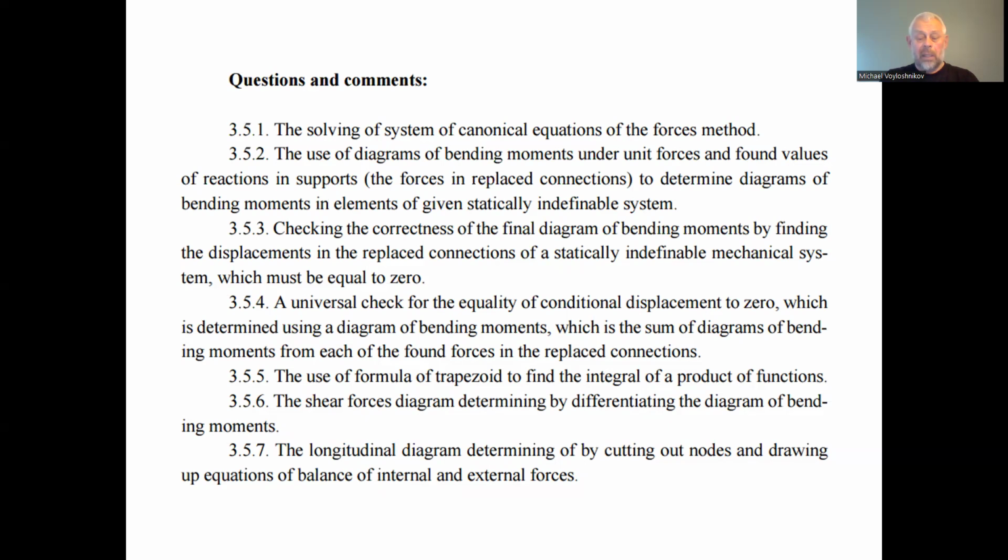Yes, it is. So what we talk about is that instead of checking the equality to 0 of displacement in each of the cutoff support links, we can check the equality to 0 of this total of the displacement in these two or any number of directions in accordance with the statically indeterminate system. In the considered system, we have only 2 degrees of static indeterminacy, so we have 2 variables, but in any case we can have many.